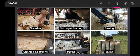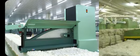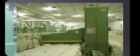So we now know how the fibers are extracted from the cotton pods and also from the sheep. Both of these are sent to the bale opening section, where the bales are cut open. Then they are blown to remove any additional dust, dirt or segmented particles. They are removed in the blow room processing. Here all the entangled fibers are detangled and made fluffy. So this is the process. Here the bale is opened. Then in the blow room, it is fluffed open, almost equivalent to the ginning process, but it is carried out by the machine. Any impurities are all removed by the blow operation.